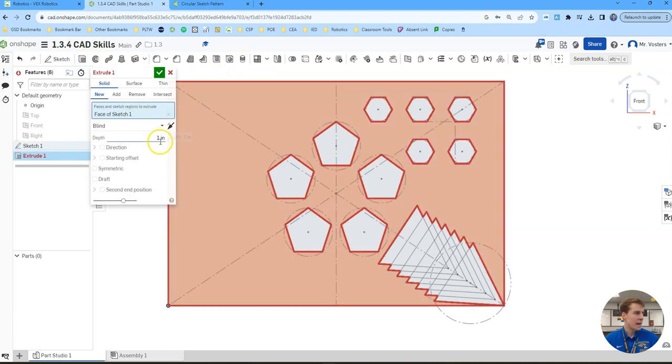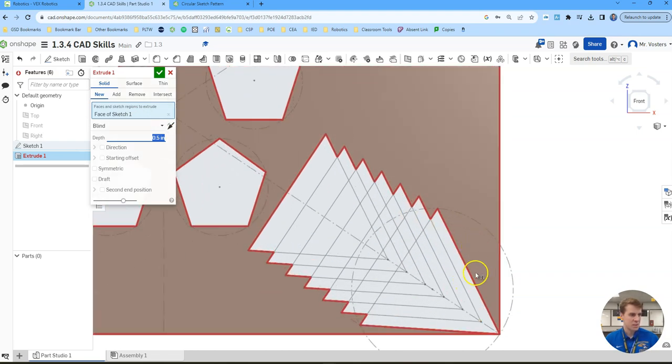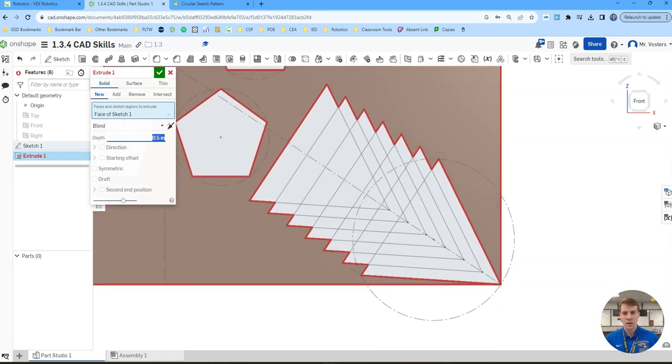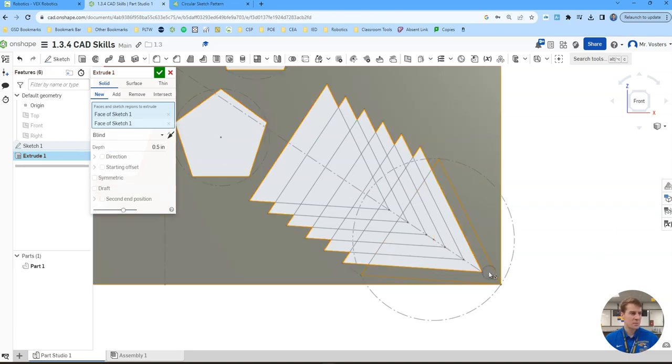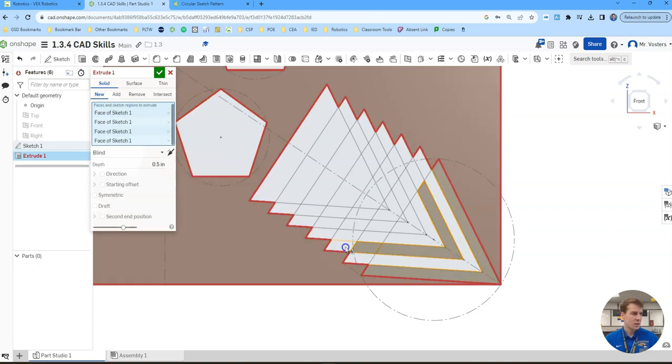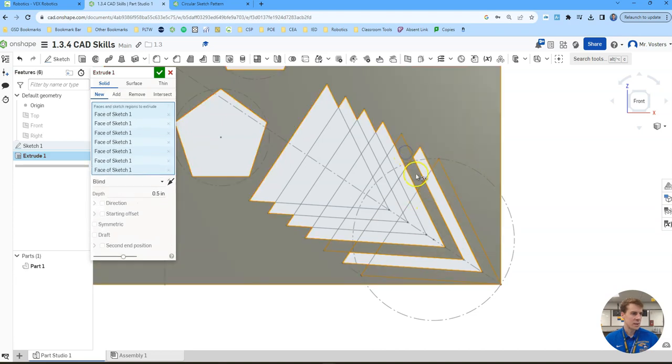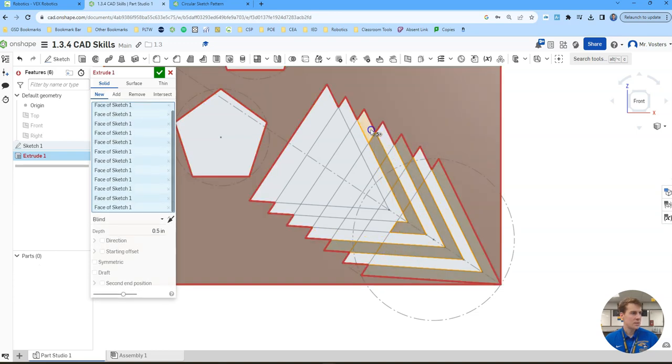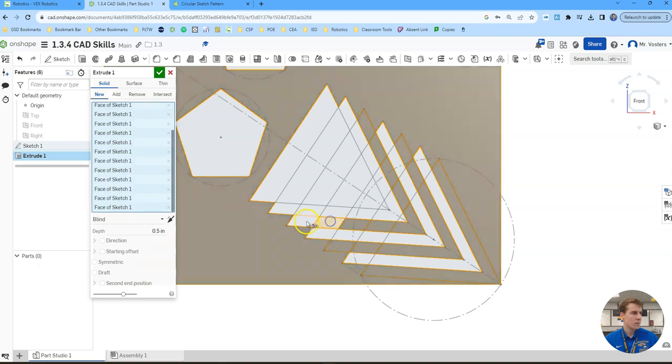We're going to extrude this 1/2 inch. And notice mine turned red. It's got something it's not happy about, and I think it's this triangle down here. So we're going to try to create this pattern where only some of these triangles are extruded, or only some slices of them. So click there. Then we're going to click in a few different spots. We're going to create this weird arrow pattern. So you'll have to click in a few places to achieve that. Just follow my clicks, and we'll fill in this entire triangle over here.